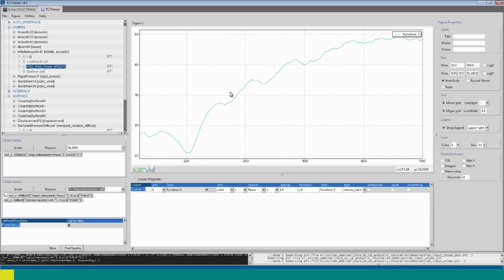But as we have some damping in the system, we don't see too much of that phenomena. And then at some moment, as the modal densities increase, we will enter a mass law region where the curve goes up with a constant slope.